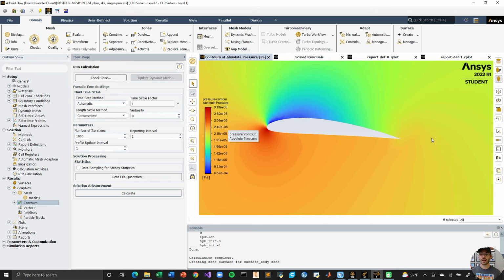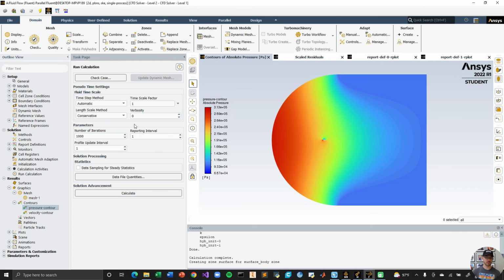And when it moves faster, because the mass flow rate has to stay the same, you can't have more air flowing. So when the air is moving faster, it becomes more stretched out across that further distance, thus producing lower density and lower pressure as a result. So that's actually what the shape of an airfoil is entirely designed to do, is produce this pressure difference between the top and bottom of the airfoil and produce that suction effect that we call lift. So that's our pressure contour.